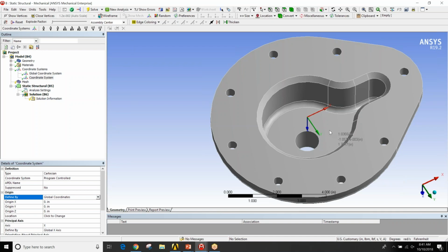After I click on it, I can move my cursor into the window and actually see the XYZ coordinates of where my cursor is. And if I click on this geometry here, you will see that location is marked. Then I move my cursor to the lower left-hand corner and click on Apply. As soon as I click Apply, it puts a local coordinate system right over here.